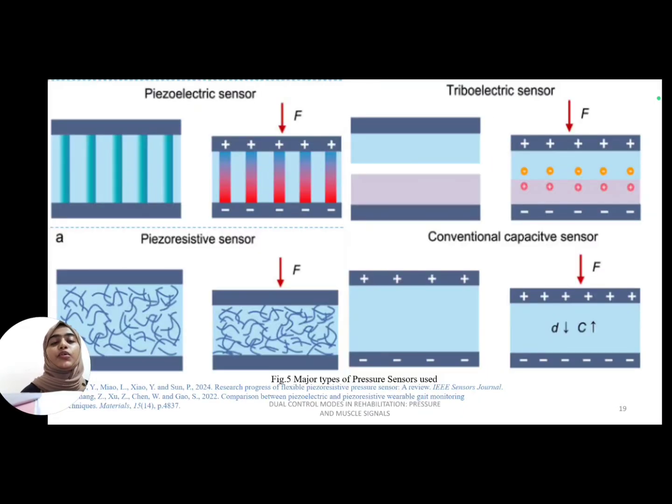First of all, we'll go to the working of the piezoelectric sensor. A piezoelectric sensor works under the principle of the piezoelectric effect. That is, when mechanically deformed, the crystal generates a certain voltage. When force is applied, the dipoles inside the material realign and create surface charges. These surface charges can be converted into force. The major disadvantage of piezoelectric sensors is that they are not able to measure static forces well, which led to the development of the piezoresistive sensor.